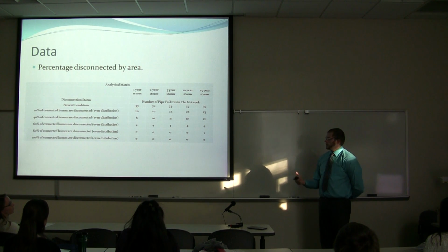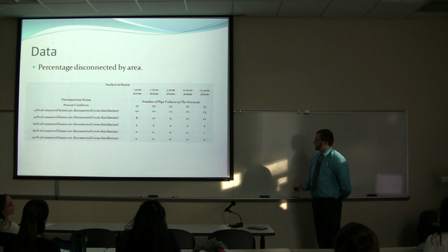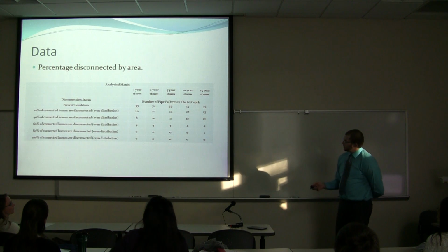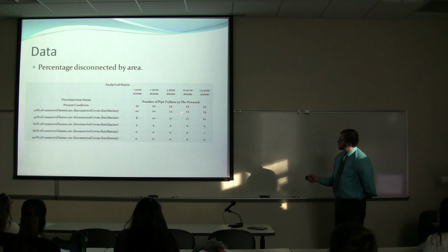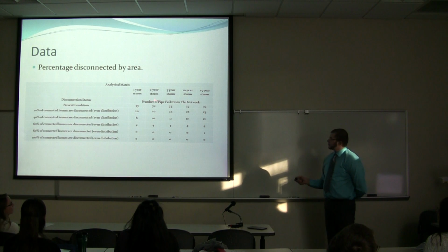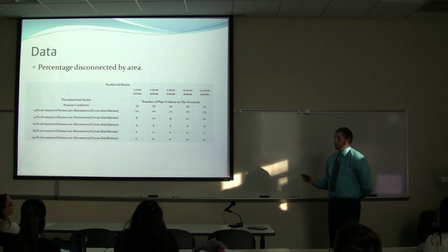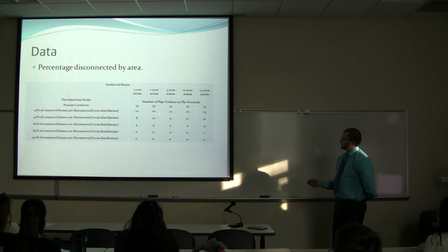So for 20% of the area, we calculated how many roofs constituted that, and then went from there. And as you can see, present conditions, for the 1-year storm, you get 33 failure areas. And with just 20% disconnected, it drops by 13.